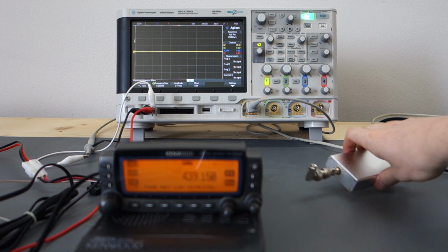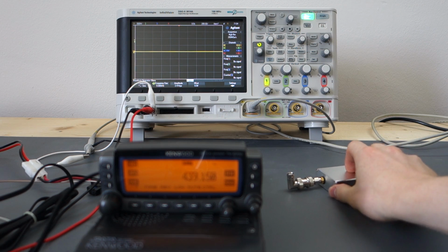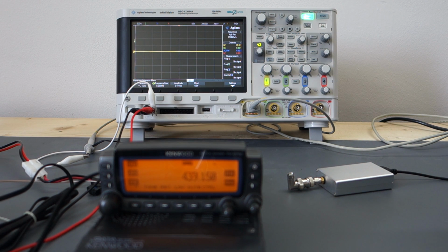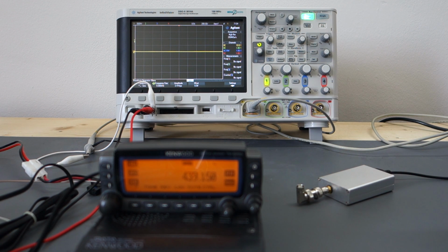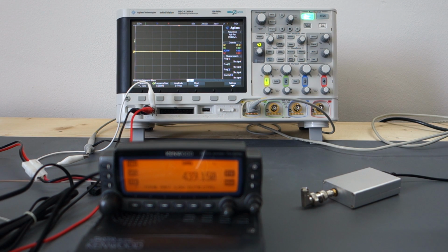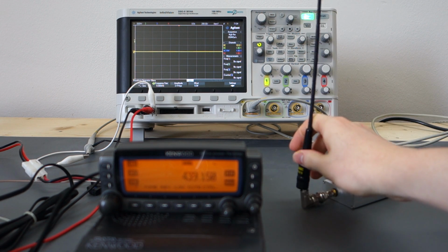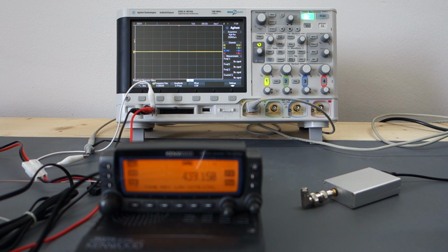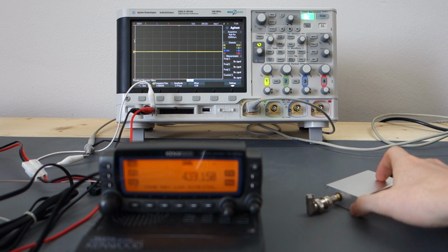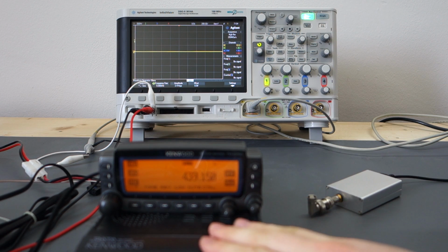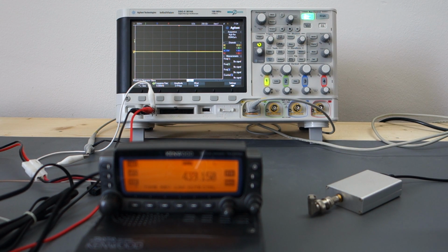I also have this little guy here, an aluminum box, and inside this box there is one of these RTL dongles that I used in the previous videos. Even though this looks a bit different than what I had in the last video, that's basically what it is, just one of these dongles without anything special inside the box. I could put an antenna on that BNC connector, but it turns out that this is generating so much stray RF that I don't need that. This is enough for me to pick up what the radio is transmitting into the dummy load, and that's what I will then use to visualize.